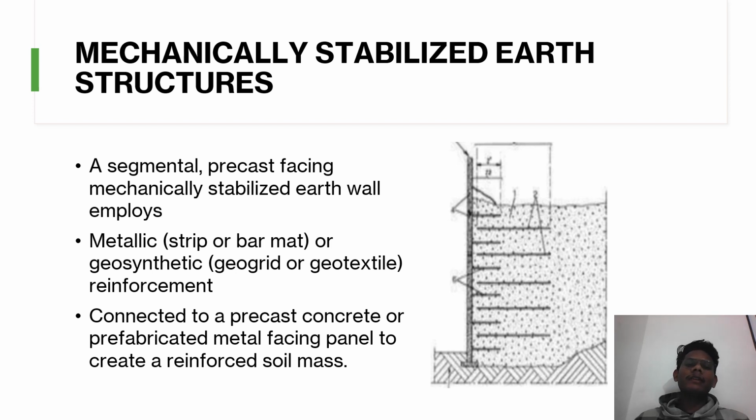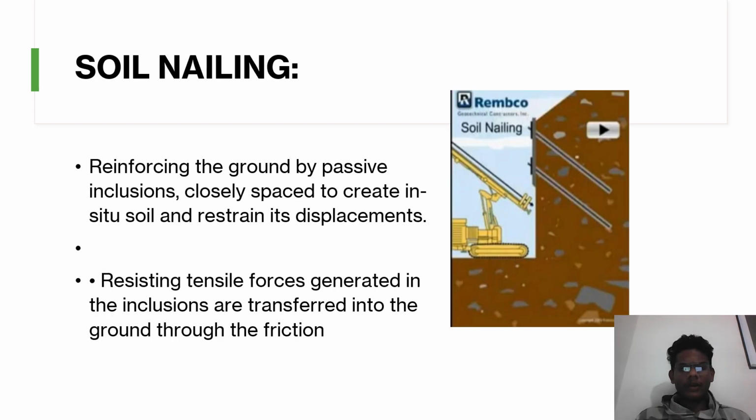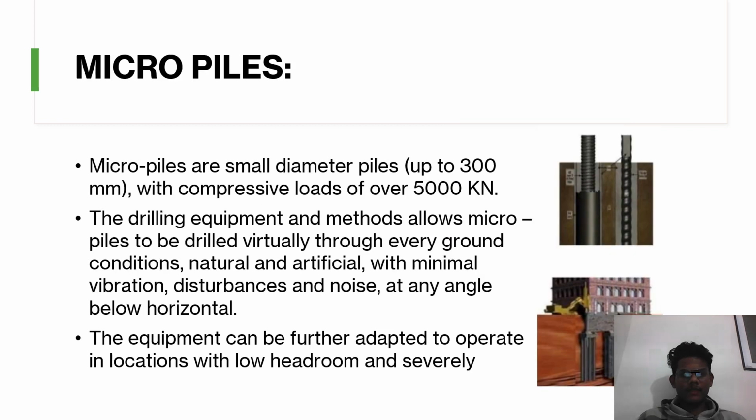Soil nailing: reinforcing the ground by passive inclusions closely placed to reinforce in situ soil and restrain its displacement. The tensile force generated in the inclusions is transferred into the soil through friction.